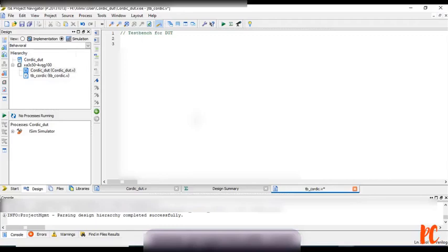As usual, I am going to start with the module name, module testbench underscore CORDIC. Now this time it is not mandatory to write the port list, since I am talking with respect to the test bench. So there is no need for me to write the port list again. Let me continue. Since I have declared a parameter there, I will be taking a local param here, which is 16, as I have already given. This defines the width of x and y.